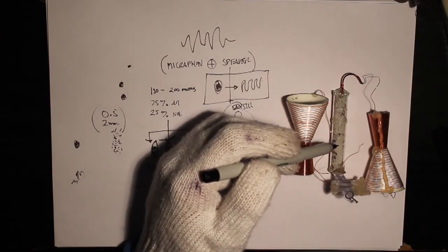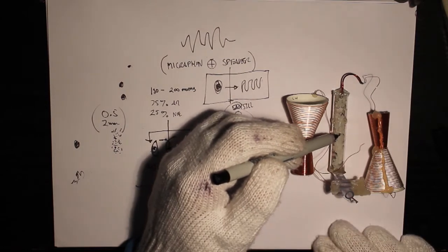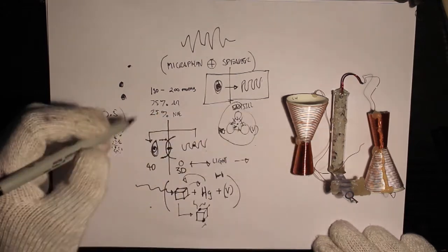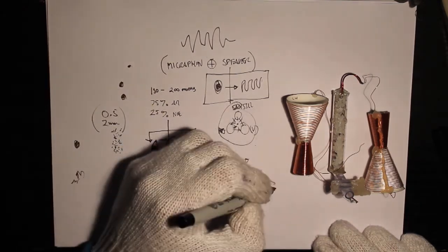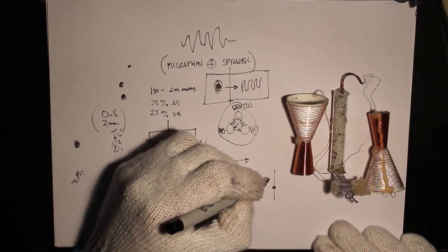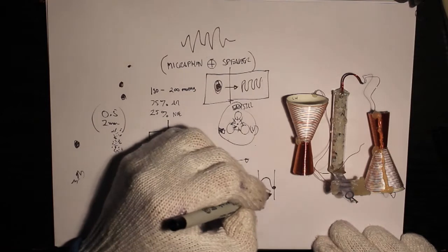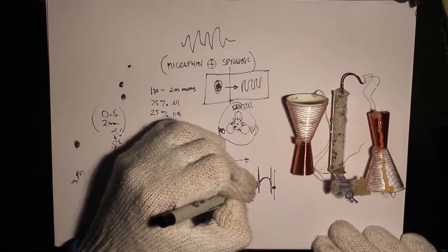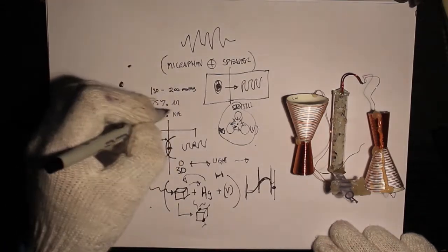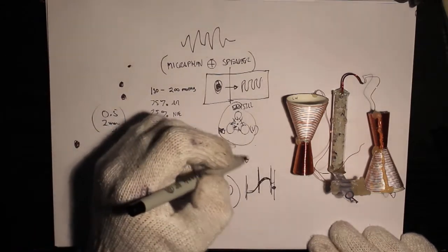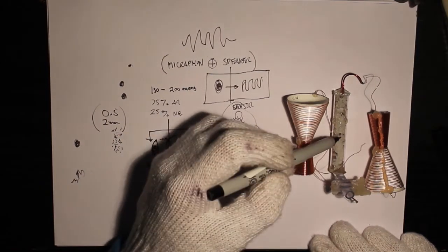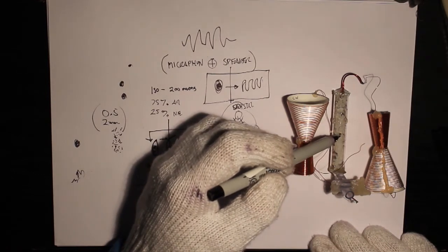It's not that fussy, strangely enough. It can't be a really high vacuum because, again, it's like the pyramid, it can't be full vacuum and it can't be too low. There's a hot spot, but the range of the hot spot is very broad. You almost can't get it wrong. But yeah, the optimum is 200 microns with the argon and neon left over in there. But yeah, the tube does work as a pressure transducer.